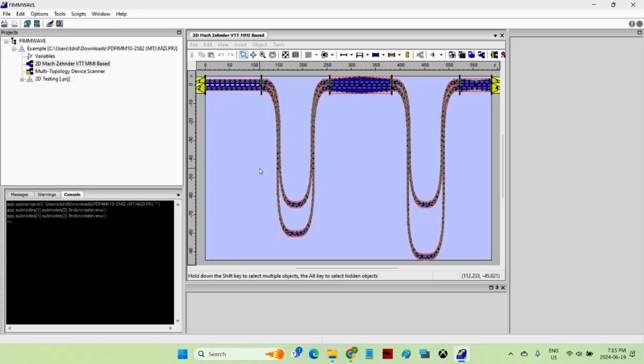First thing to notice in this example here is the scale. So on the top here we're going up to 600 microns, and on the scale here down to about 100 microns. So a reasonably large simulation area. Certainly one that, if this was a 3D simulation, would take a lot of computer power for FDTD to solve, and until now would be impossible with EME, and in addition also impossible with beam propagation methods.